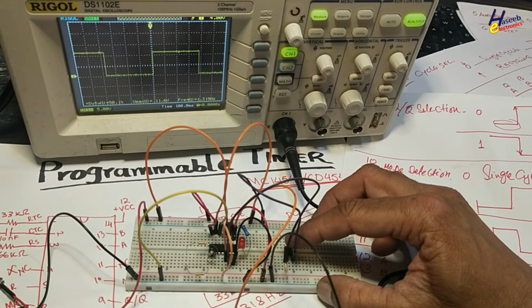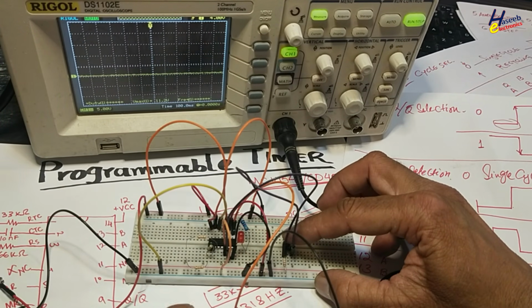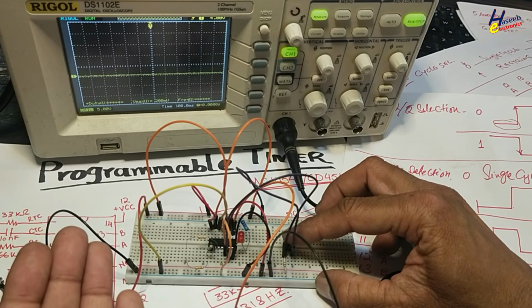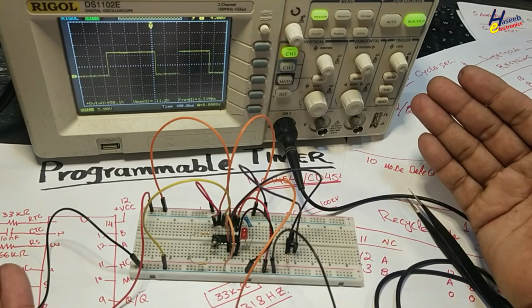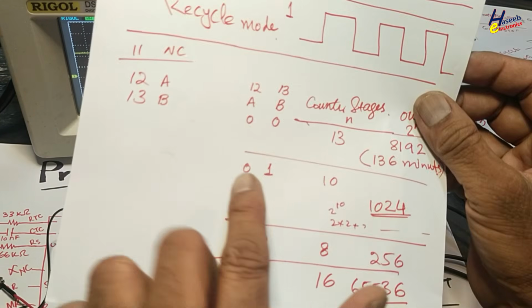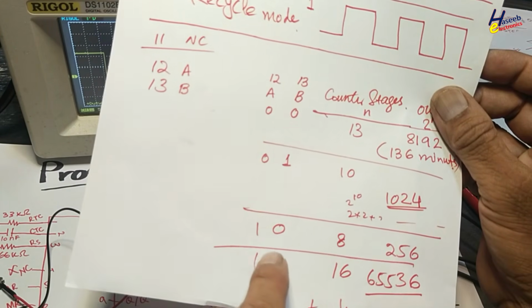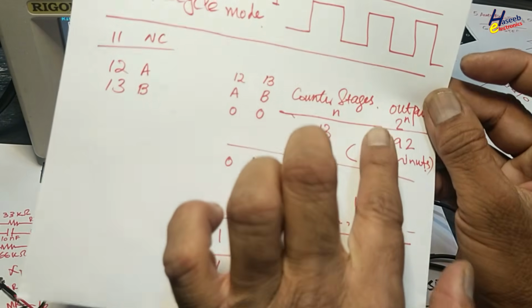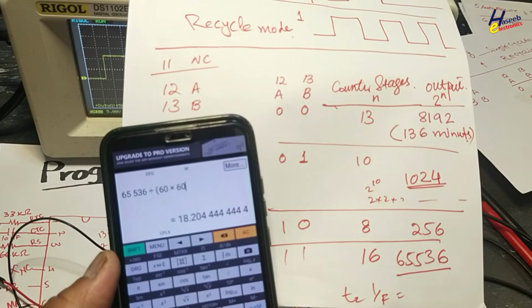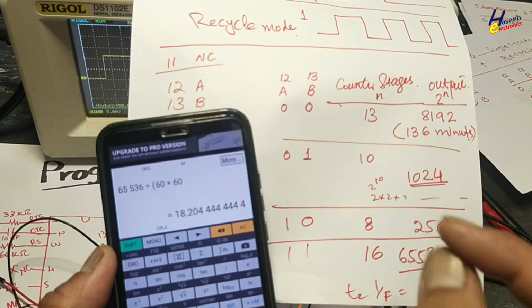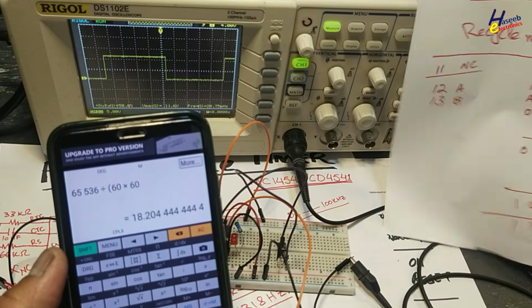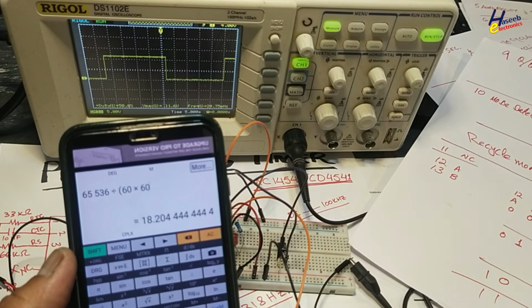Anytime we press the reset button, the IC will go in reset mode. Output will be disabled and it will start counting from 0. Let's design this circuit. We will divide the frequency using these binary inputs. Input frequency will be divided by these numbers by selecting these binary inputs. If we provide 1 Hz frequency at input, this IC will provide output after 18 hours.